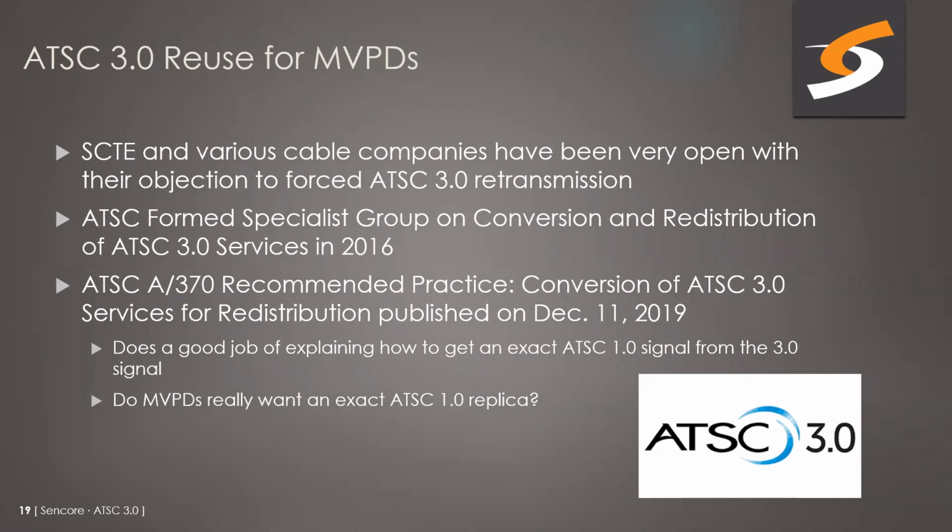And suddenly the broadcasters are on the air with a signal that's not really compatible with the MVPD networks in any such way. Like we talked about, there's no longer a transport stream. There's HEVC video compression, which I'd say most MVPD systems' set-top boxes don't support at this point. AC4 audio is the same way. Captions are definitely another big consideration there.